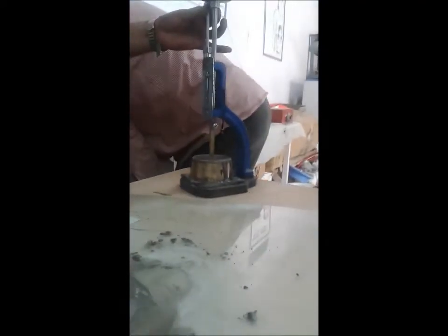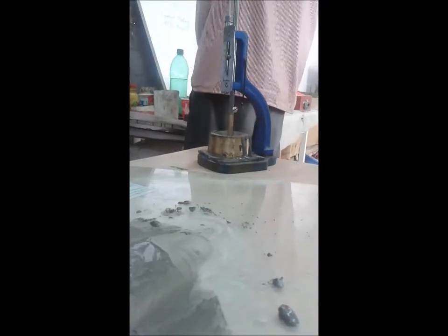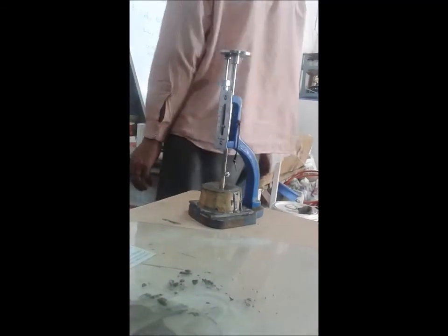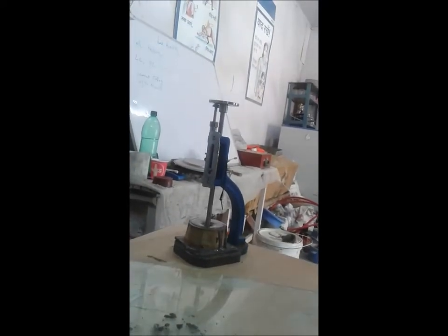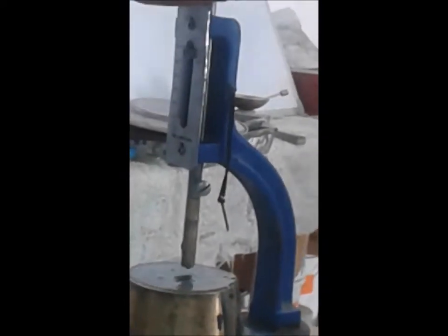Replace the needle of the Vicat apparatus by the needle with an annular ring. Lower the needle and quickly release. Repeat the process until the annular ring makes an impression on the mold. Record the period elapsed between the time of adding water to the cement and the time when the annular ring fails to make an impression on the mold as the final setting time.